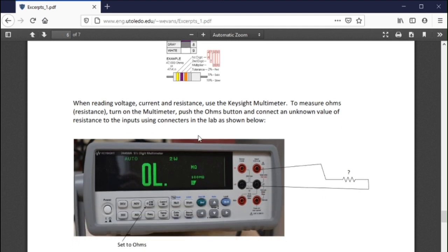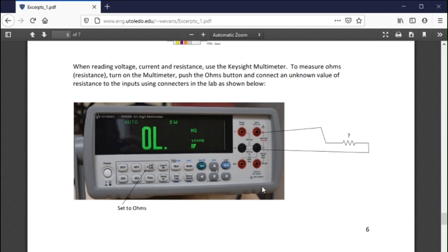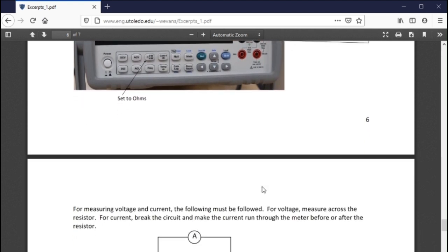And this is how you would measure resistance. You would use the VOM and set it to ohms, and then you would wire out from the one and put one side of the resistor, and then the other side of the resistor goes to the neutral. So out from the plus, and back at the minus. I think right here, you would click this machine to ohms, and you would be able to use a clip lead to come out, tie it to the resistor, back from the clip lead to the neutral, and you're all set. And you give your reading, and that's how you do your labs.